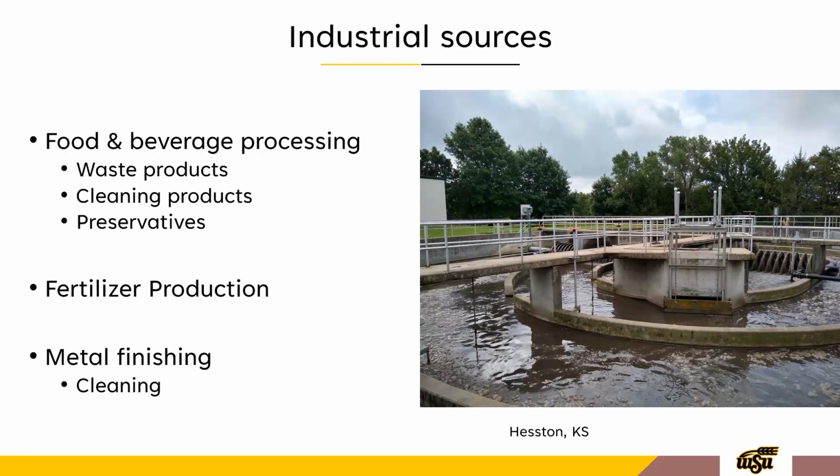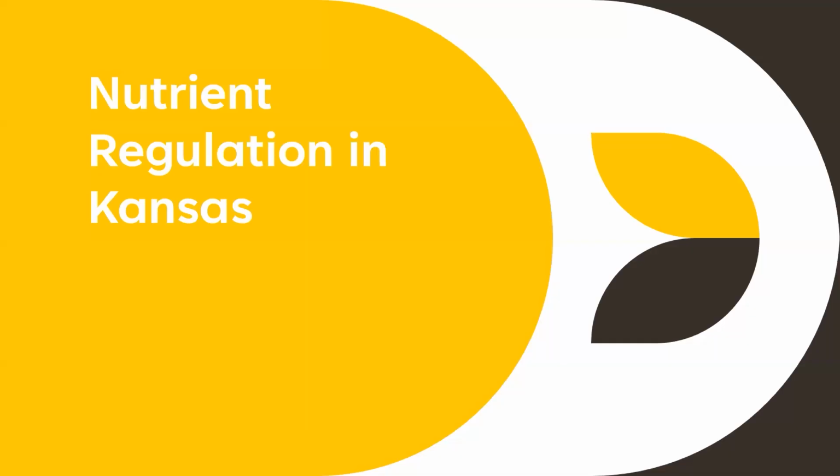That's when you catch it. I've seen influent phosphorus levels of 60 to 90 milligrams per liter. I don't think that's typical, but that is the information that the plant has. So oftentimes more data is going to be needed if you're suspecting high loadings from industrial discharges.